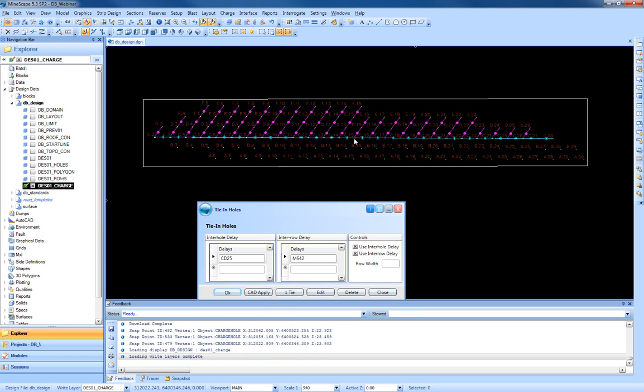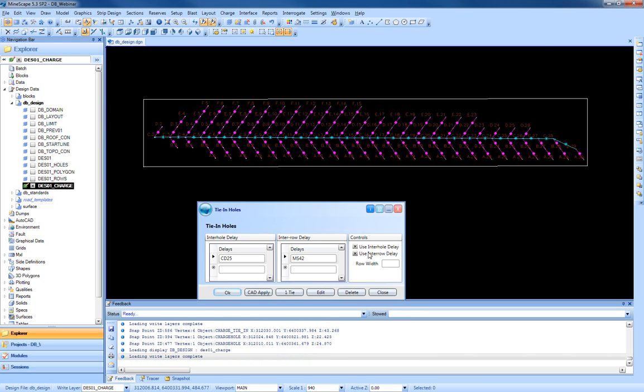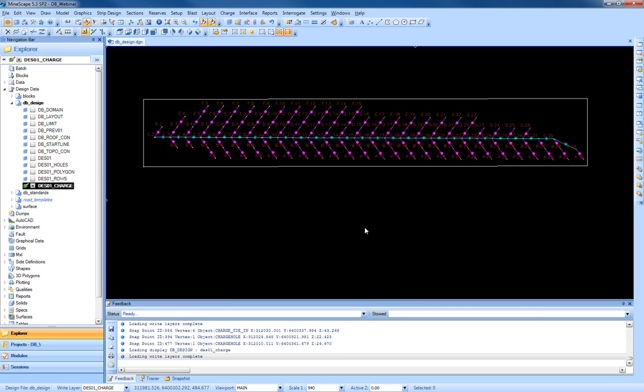Okay, now I just do this again for the second batch. So I select that hole, and then we'll go to that hole. Okay, so after that, you need to calculate the detonation times. You need to go to the blast and then go to the blast annotation area and select what you need to annotate it, because then you can see the cumulative and detonation times within the pattern.